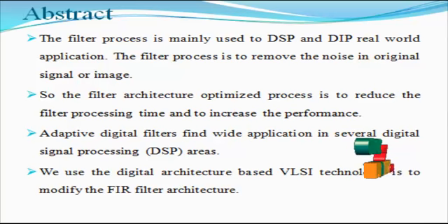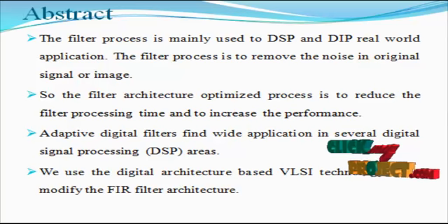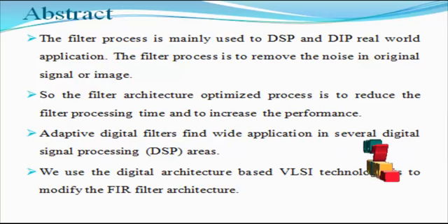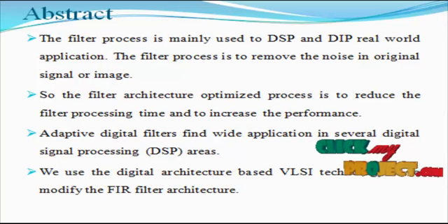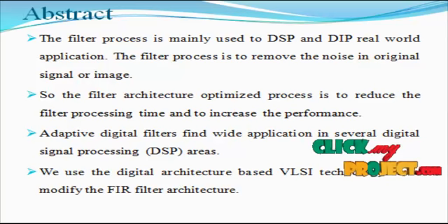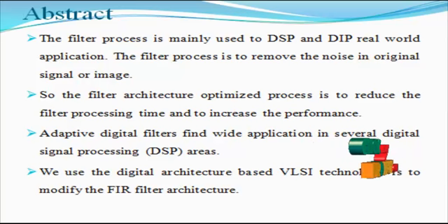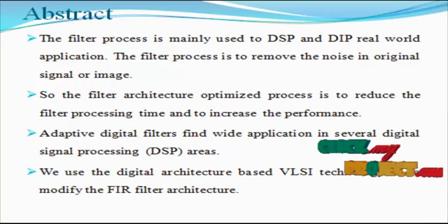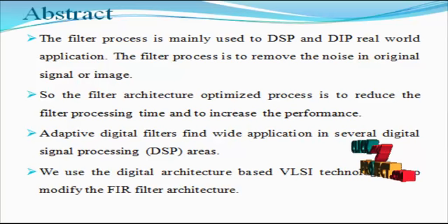It's shown that the direct form of the LMS adaptive filter has nearly the same critical path as its transpose form counterpart but provides much faster convergence and lower register complexity. From the critical path evaluation, it's further shown that no pipelining is required for implementing the direct form of the LMS adaptive filter for most cases, and it can be realized with a very small adaptation delay in cases where a very high sampling rate is required.